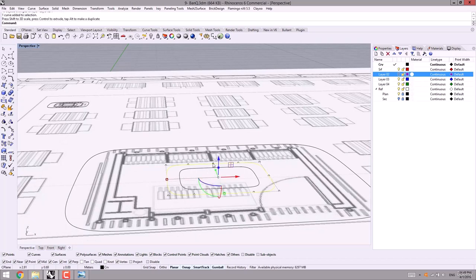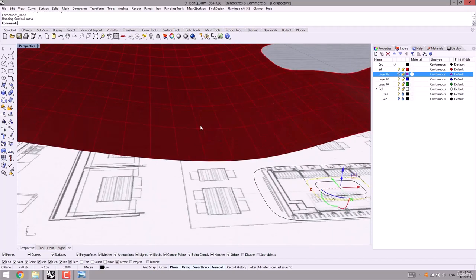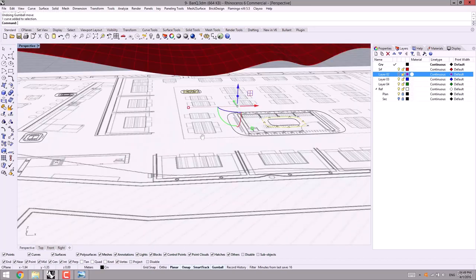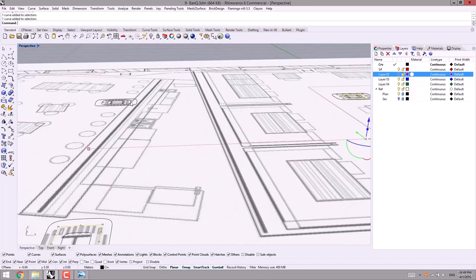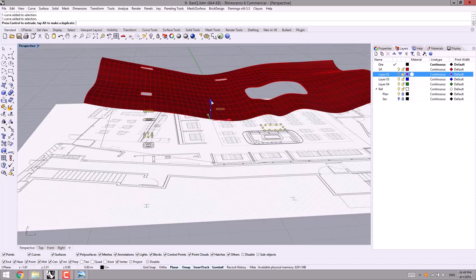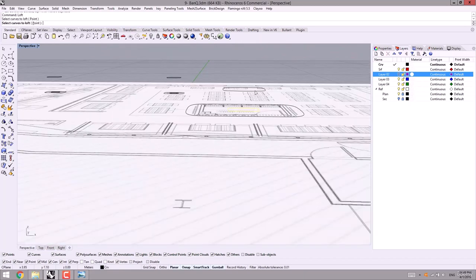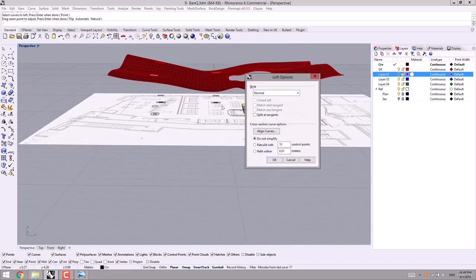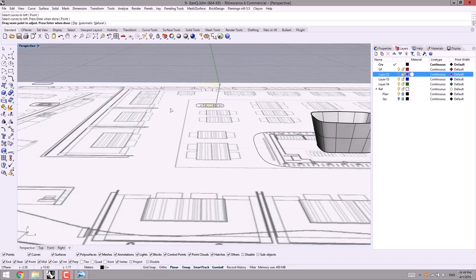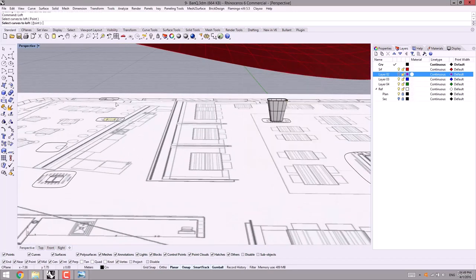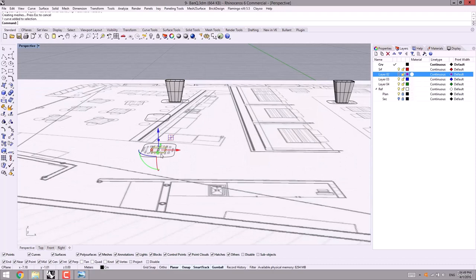And then back to the project. Here I select these and I can minimize them by scale, and I revise some of the control points. I move it upwards, and then for the column, I select these three curves and move them upwards equally. Following that, I start loft, then I specify the closed curves to create the surface. This way I move on.